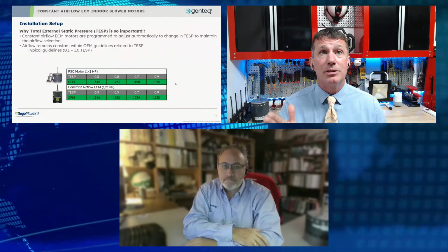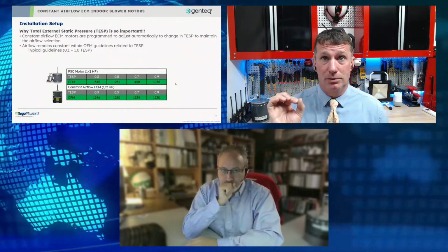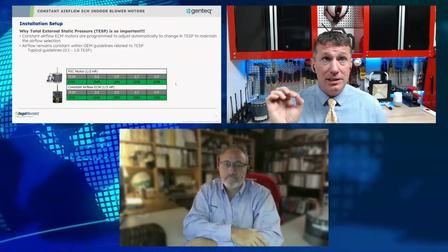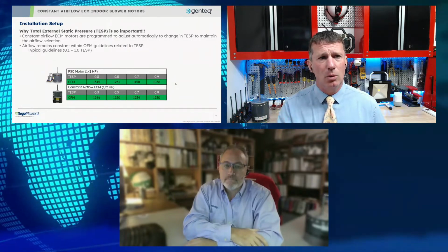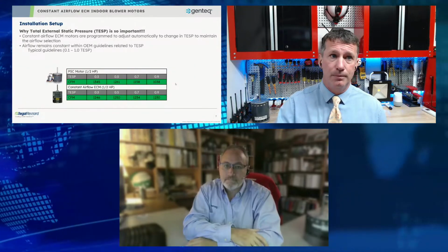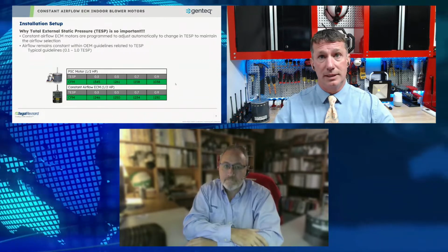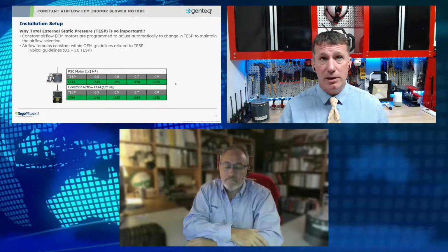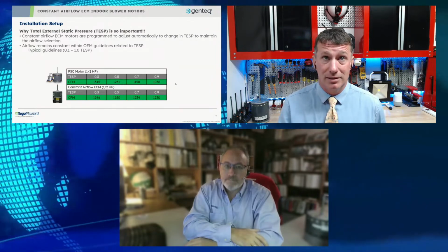I've seen manufacturers set consequences as detailed as blower fault codes, so that once it reaches that point, it is going to go into self-preservation mode. And the contractors go, well, why is it doing it? And I said, well, why wouldn't it? It's smart enough to protect itself, and it's trying to overcome improper installations or failures within ductwork or things that have been changed on the system. So it's very critical to know the capabilities of that motor. It's not going to run forever. It's not going to overcome.